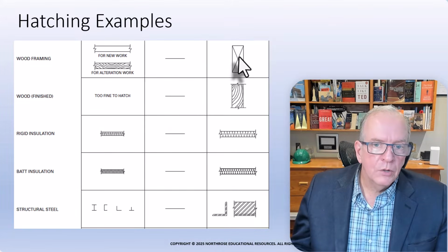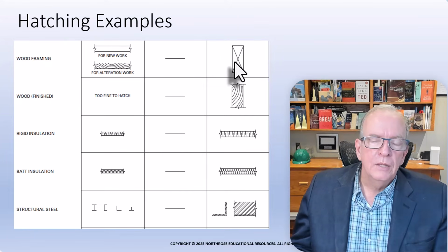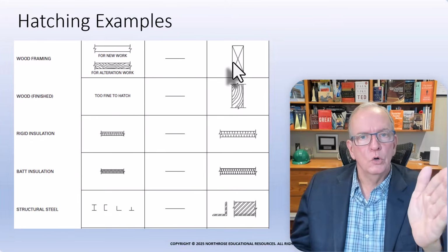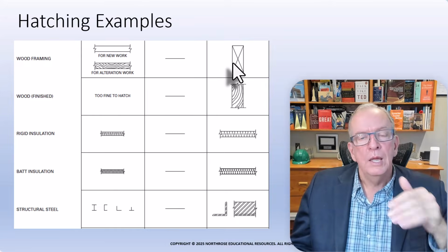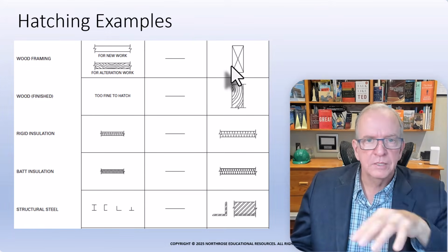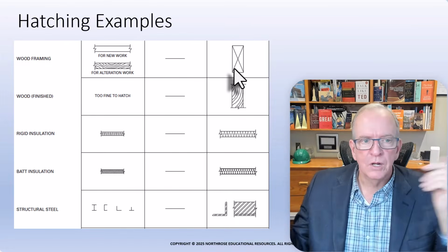Wood framing material. This is like if I cut through dimensional lumber and I'm looking at the end of it. So if I see the end of a piece of wood, usually in detail drawings you see this a lot, where it might show the rim joist, right, that you've cut through it. It might show the sill plate with an X, that basically, okay, this is the sill plate. It's sitting on a concrete wall. It's got a rim joist, and then you just got a regular joist.